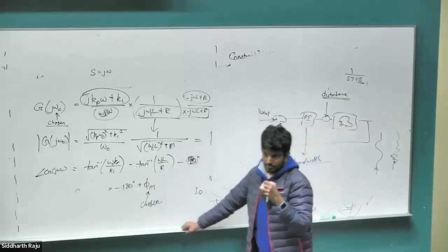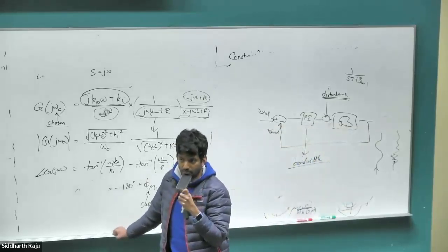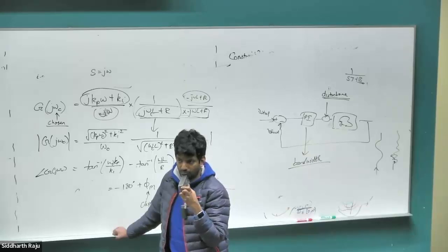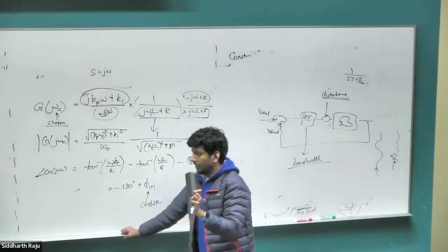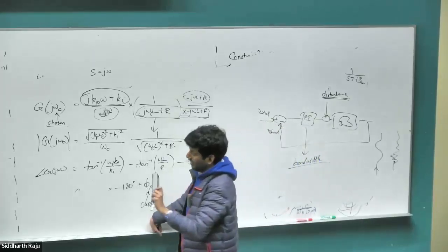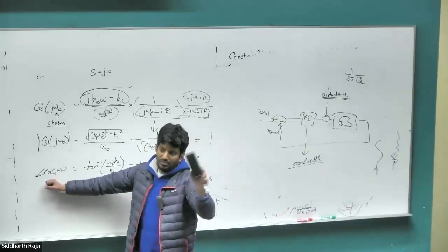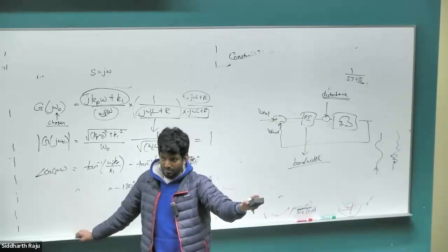Yeah, okay. Why is this G of s and not C of s? Don't you have a controller in there, so wouldn't that be the closed loop transfer function? No. So the Nyquist stability criterion that we had was analyzing the phase margin. All of those were defined for the open loop transfer function, which in turn dictates the stability of the closed loop transfer function.